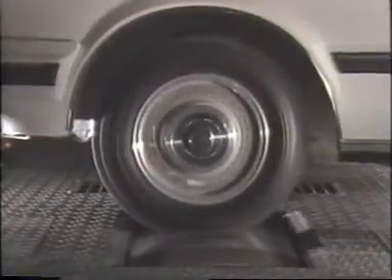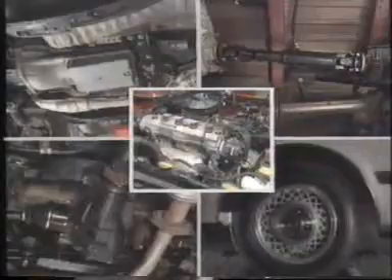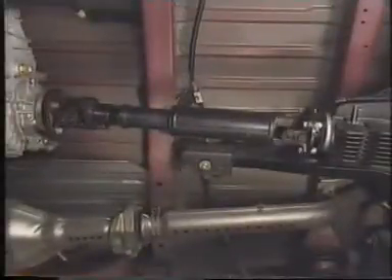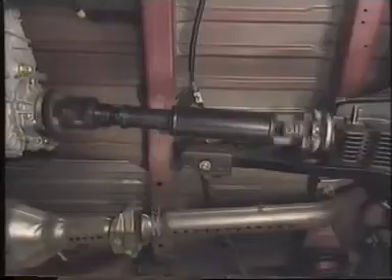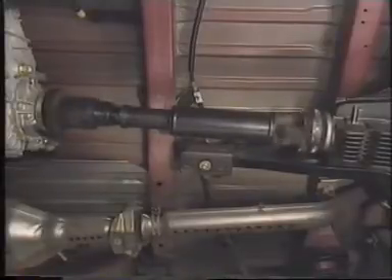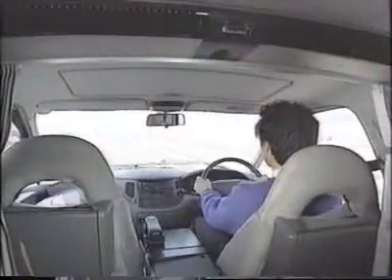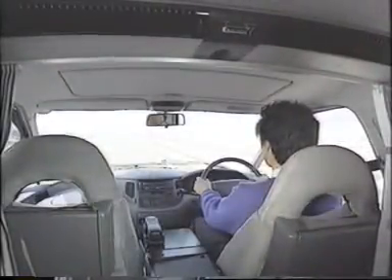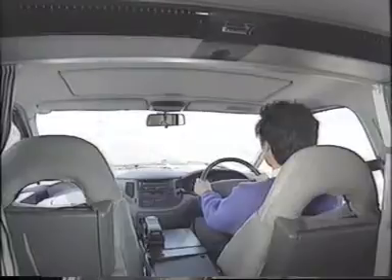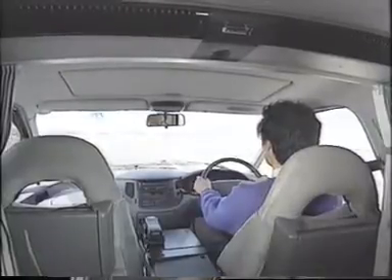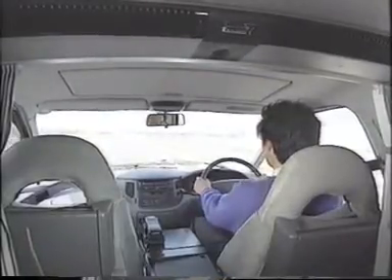This can, in turn, cause the body of the vehicle to shake. An unbalanced propeller shaft also causes vibration each time it turns. This can cause a droning or humming noise called booming, as well as vibration when the car is running at a high speed.